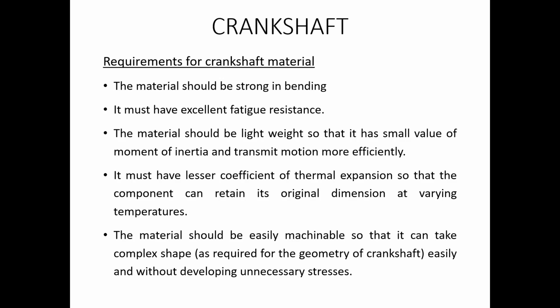and it should be lightweight so that the moment of inertia can be reduced and motion can be transmitted more efficiently. Since the temperature inside the engine also remains high, the coefficient of thermal expansion should be low so that it does not change its dimensions at different temperatures. And also it should be easily machinable so that it can be machined into complex shapes.